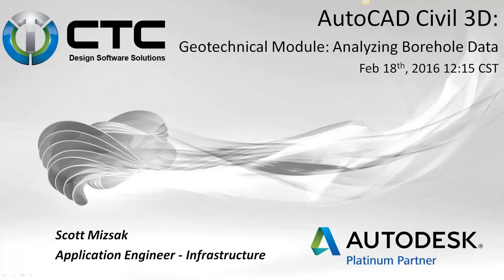First of all, the Geotechnical module is for soil borings. It allows you to take data from an Excel file and drop it into Civil, and then potentially create surfaces and profiles from the data based off of where each layer of material begins and ends. So I might have 15 soil boring holes, and if I know where the top of clay is in all 15, I can actually generate a surface called top of clay. So that's what it's intended for.